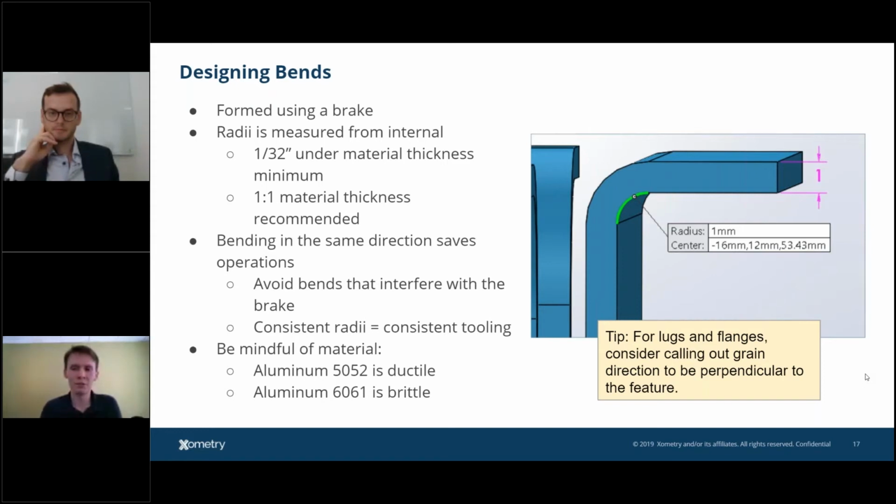there are ways to resolve those minimum flange lengths, but basically the goal there is leverage on the other side, plus a little bit more, and there are some equations that can help figure that out, especially if you're actually a press operator. And your flange width itself should be about 4x material thickness. But this is all about me being able to get this feature into a tool, secure in a location where it can have leverage on both sides to create that proper formed shape.